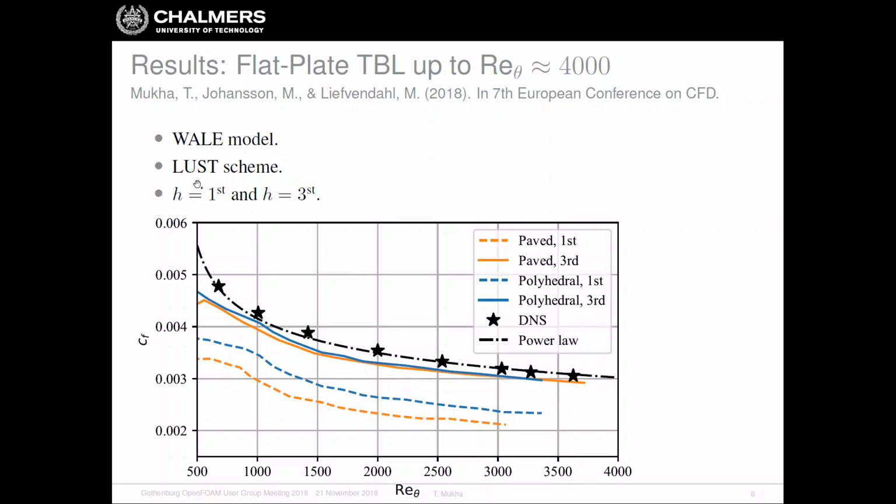So when we sample from the wall adjacent cell, we get an underprediction of CF. And that is the reason why it's not recommended to use the wall adjacent cell for sampling. This has been seen both by us, and first before us, systematically across many different types of solvers based on different numerics and so on.